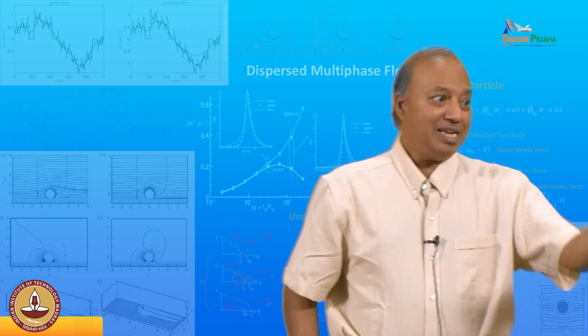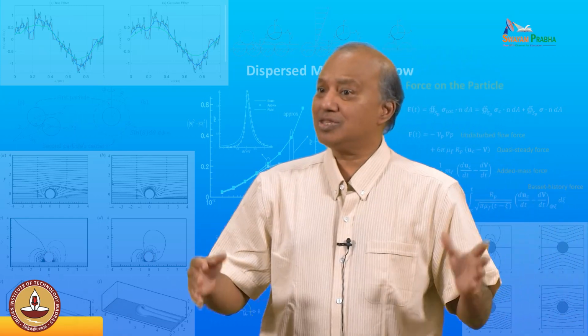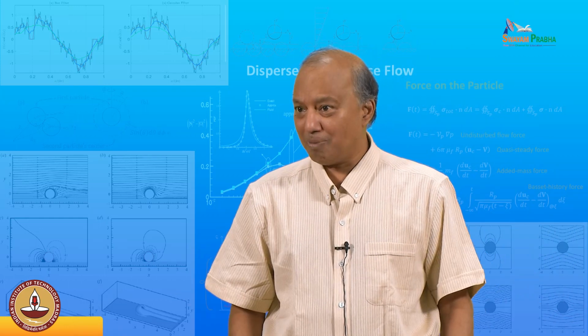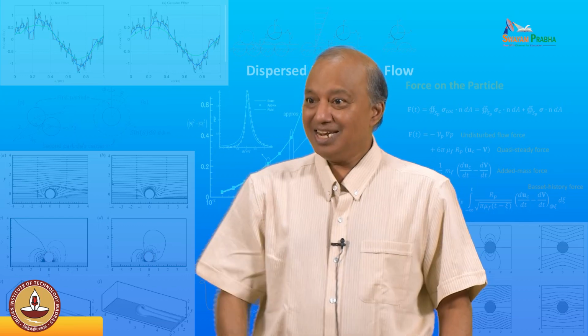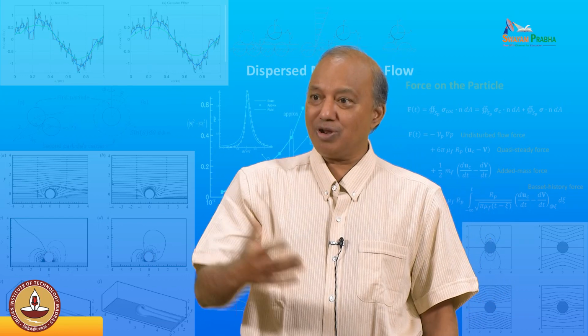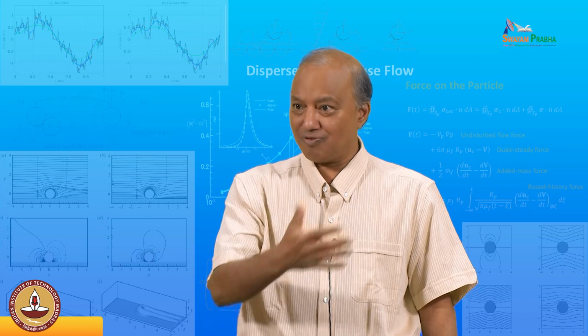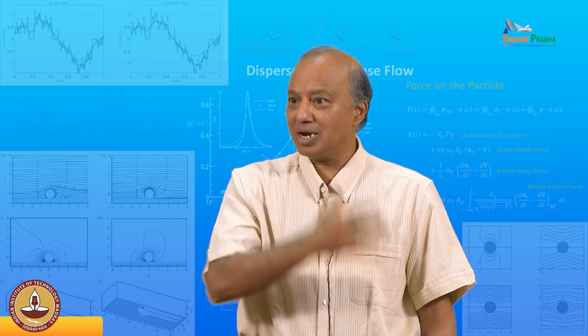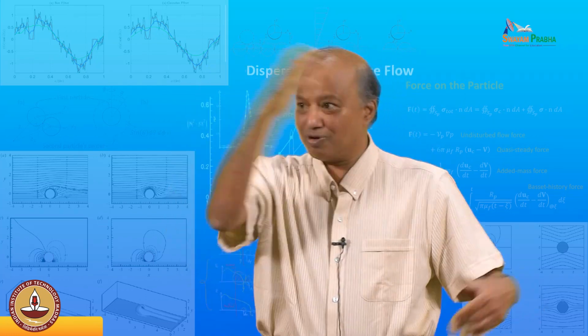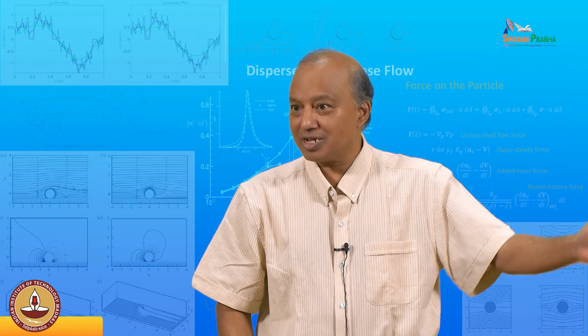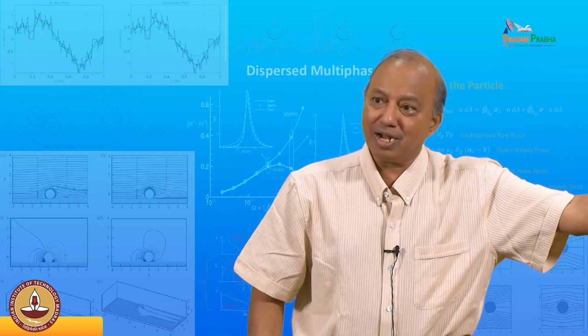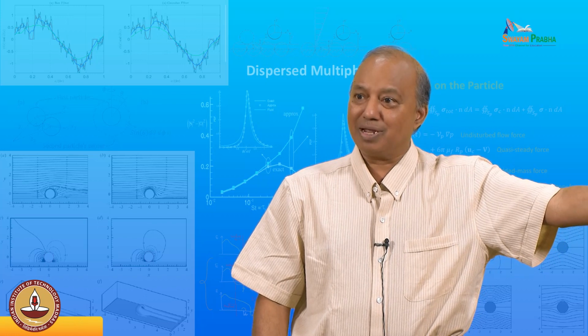The other thing is, whatever I told her is another great way. Just assume two-way coupling, you put it in there. Now you calculate your Navier-Stokes equation. So in ANSYS Fluent, you ask it to plot the advection term over a domain, you ask it to plot the viscous term, and you ask it to plot the two-way back coupling force term.